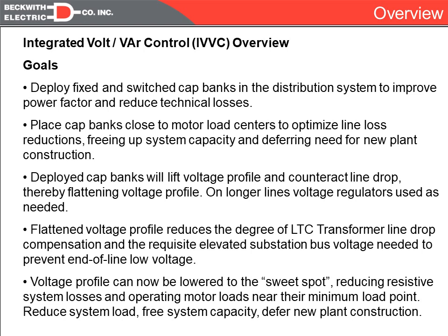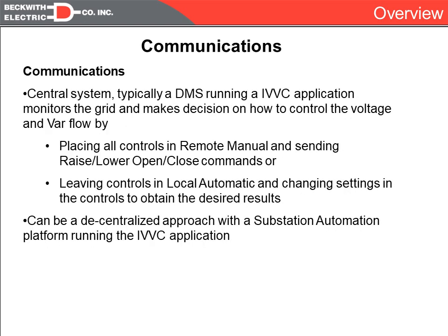And as we discussed in the last session, session 4 on architectures, there are two basic approaches to accomplish this. One would be using a system where no communications is in place and we're coordinating the operation of the regulators, LTCs, and capacitor banks via settings in each control. And the second approach would be a more centralized approach with communications, where we have a separate software application that is collecting data across the entire system and making decisions as to where the best place to raise or lower the voltage is. And so in this session we're dealing mainly with communications.